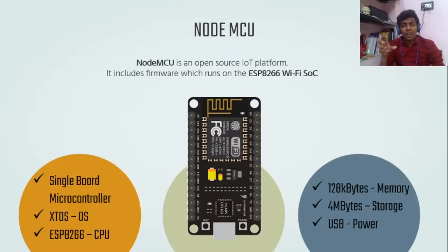So that FlashMagic application will be helpful for uploading that exported .hex file to the IC. If you take the Arduino Atmega, we need to burn that program into the Atmega IC. So for that we'll use external software. If you take the IDE, integrated development environment, it has an inbuilt compiler as well as an uploader.